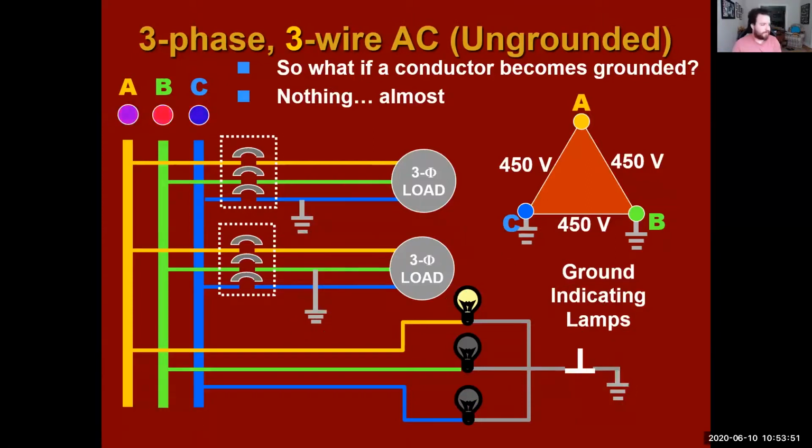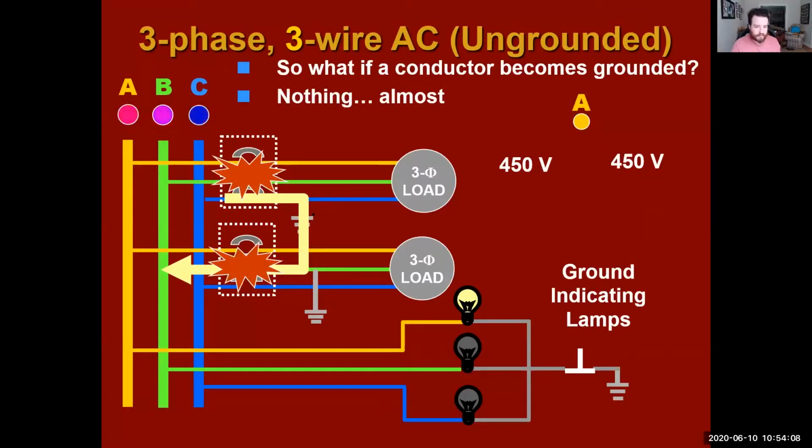If you only have 1 ground, it's not really much of a danger. Just go find it. We'll talk about finding it in a second. But if you have 2 grounds, this is when you're going to have that problem. You might as well, like I said, attach a wire from this run right here to there. And that's how you blow those circuit breakers, and you trip them open and you lose power to certain portions of the ship, because too much current is going through. You lose B and C. They're gone.